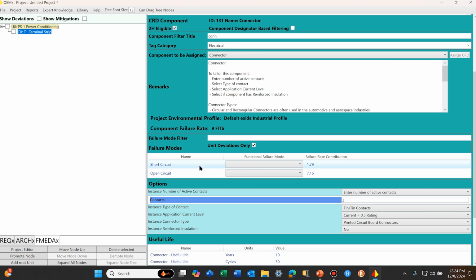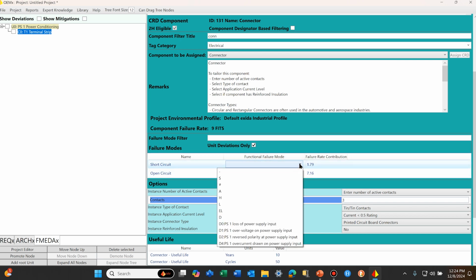Now, I have to map this component failure mode, short circuit, on the connector. Let's assume worst case, plus to minus. Well, we're certainly going to lose power, and there's probably going to be trouble upstream, but we could just right now call that dangerous if we know it, but we've already done the work. So look at this. The failure modes of this block are presented for us.